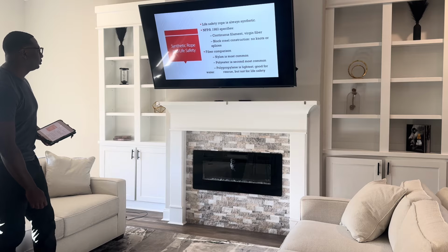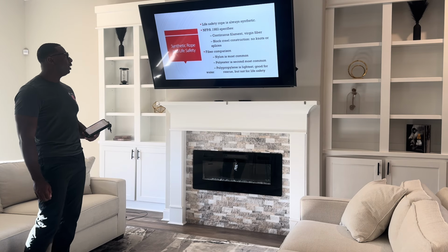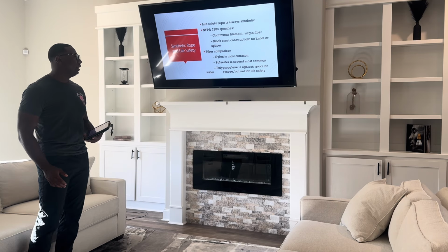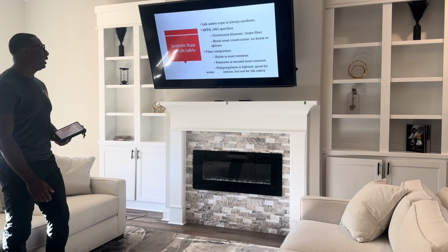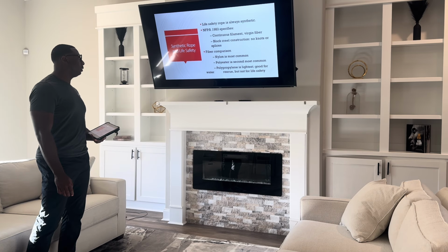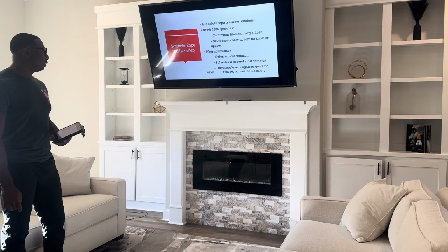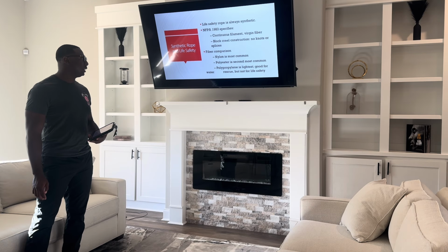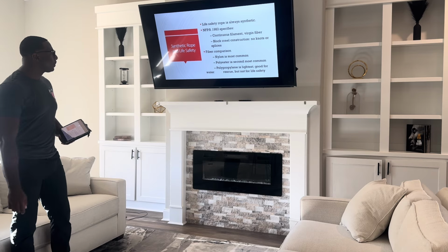Synthetic rope and life safety. Life safety rope is always synthetic. NFPA 1983 specifies that it is always continuous filament virgin fibers, block creel construction, with no knots or splices.